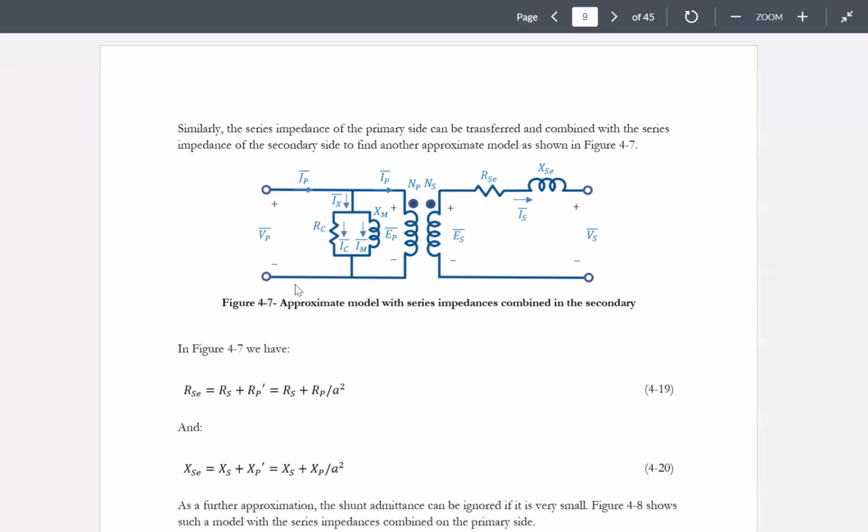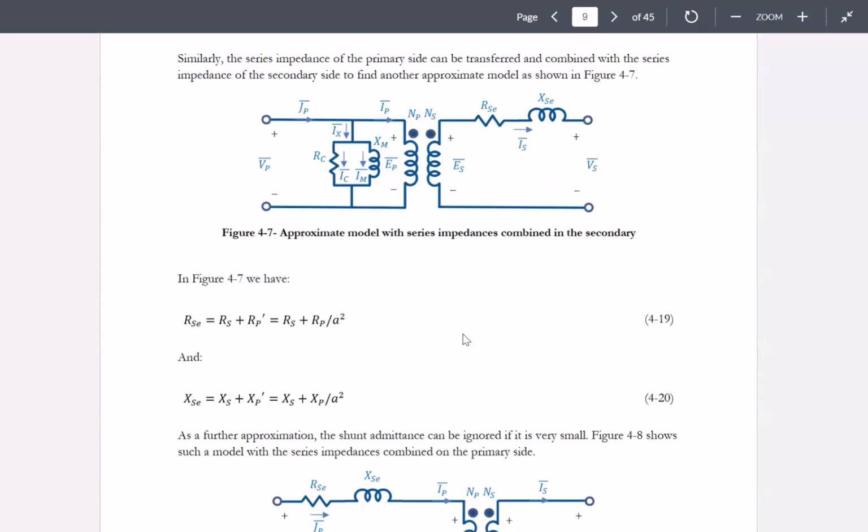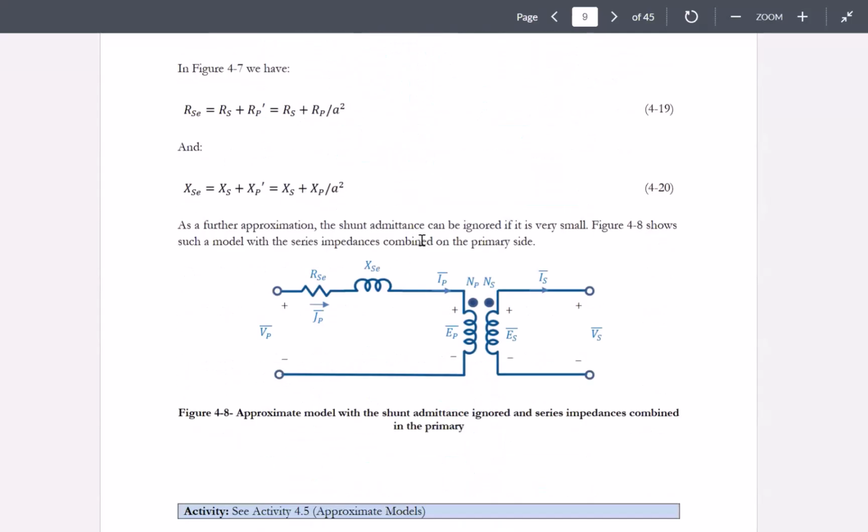Power needs to be measured in here. Keep in mind that your wattmeter should be a really delicate wattmeter because you're open circuit. Therefore, the amount of power consumed through this path would be very small. So it's really important that you have a good wattmeter, which sometimes they call a compensated wattmeter. Those are the types of wattmeters that are more expensive and have extra components to account for the inaccuracies in the measurement.